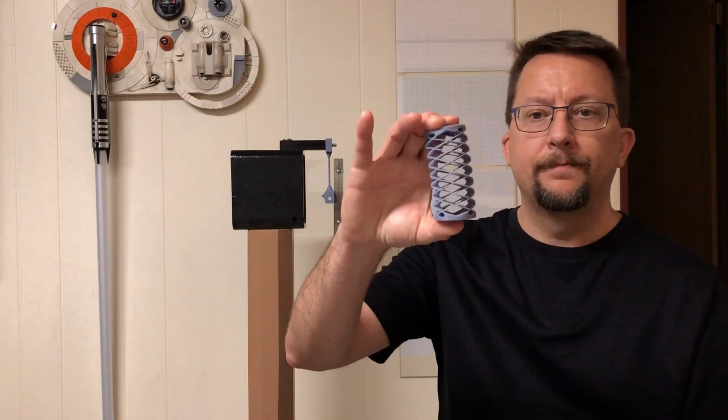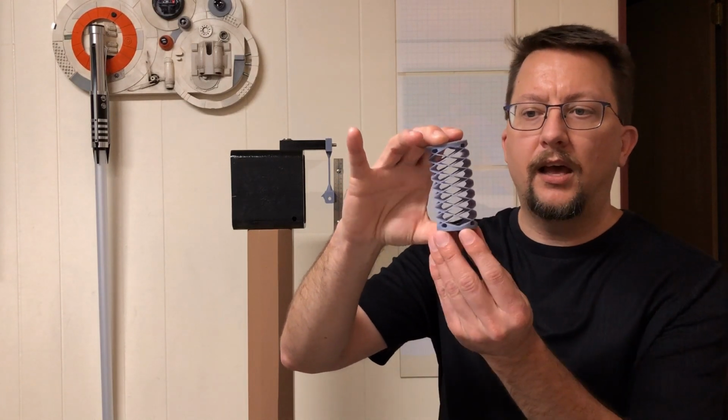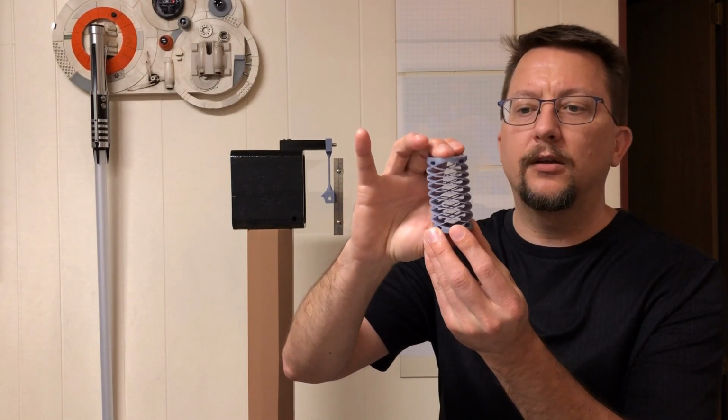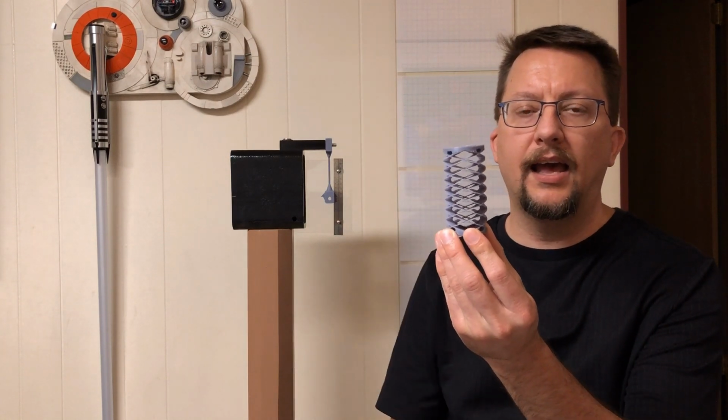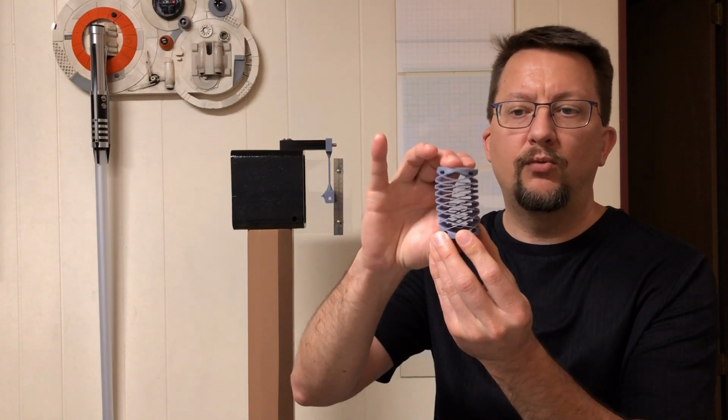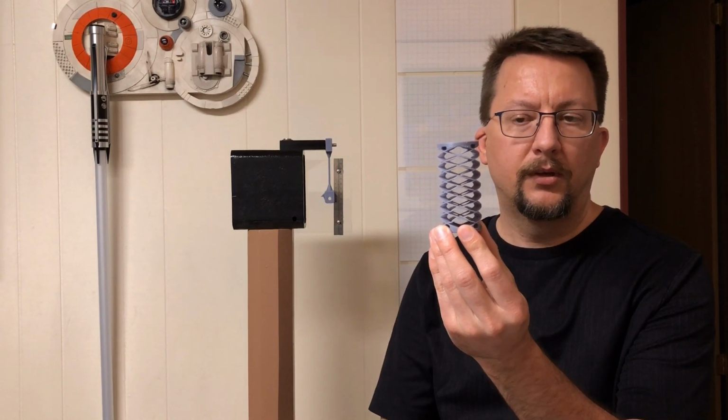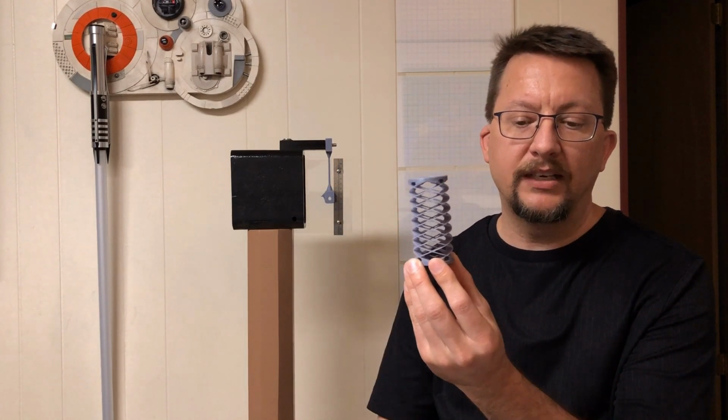Now, for our resins, do I think it will act like that? I'm hoping, and I think we'll show this, that there is some sort of elastic range early on. And I can say that because I have designed a spring and I've printed it out, and this isn't fully cured, so it's just out of the printer, but I can stress it and it will return to its original shape. And actually this guy, the reason we did this is we're going to study how curing changes its resilience over time, and that's what he's for. So that's a little further down the road.